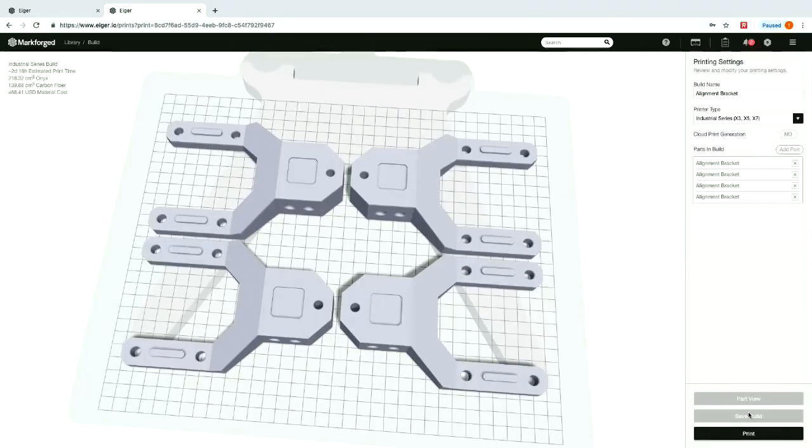Okay, and then Saber Tooling asks, sorry, I may have missed this, but does the part automatically core out solids? Yes. Like most slicers, our software takes in an STL, which is just a solid body file that's a series of triangles. It doesn't have any information about the CAD or how it's designed. It's just a solid body. It then finds the shell of the part once you orient it, assigns roofs and floors, which are the tops and bottoms of the part, assigns the walls of the part, and then fills everything that's not a roof, a floor, or a wall with triangular infill. And that triangular infill is coring it out.